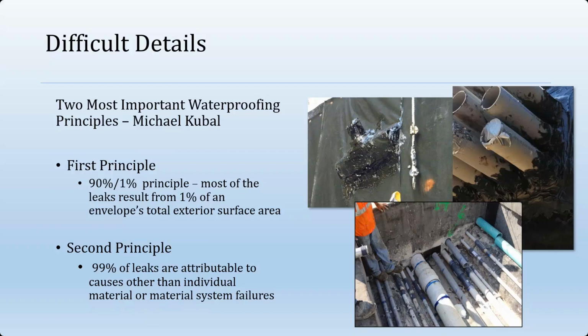encumbrances. We typically flash a pipe, whether it's a below grade foundation or a roof vent stack, pretty much in the same manner. We have 3 inches of the flashing onto the substrate and 3 inches onto the pipe penetration. Now, I realize, again, I say that's wishful thinking. It's often not possible where, unfortunately, we're faced with having to cluster pipes ever closer together. And in many cases, they're actually touching each other.